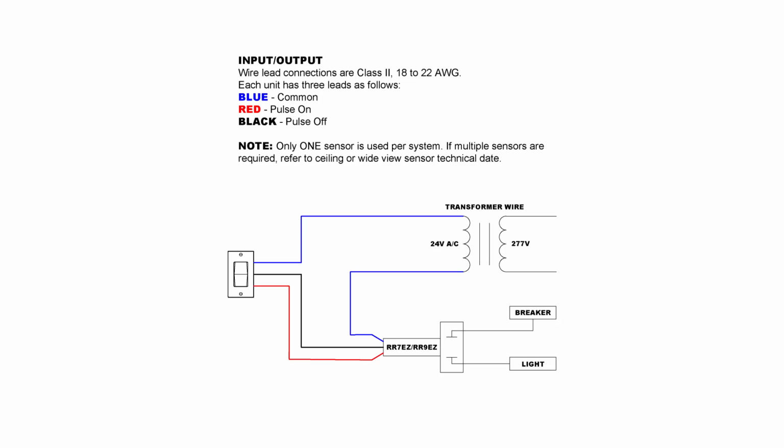Okay. Now we're going to be looking at the actual light switch connection to the relay system. So on this graphic here, you have a light switch, the 3 different colored wires. Once again, red on, blue off, black common. Here you have 3 wires on the relay. This is the relay here. This here is your light bulb on the high voltage side.